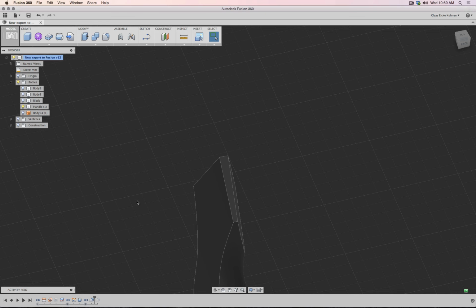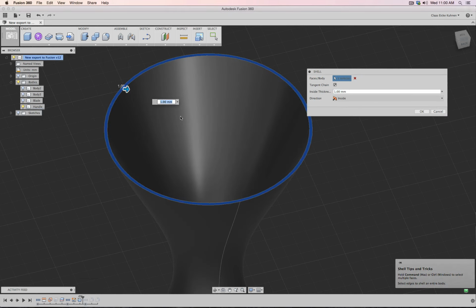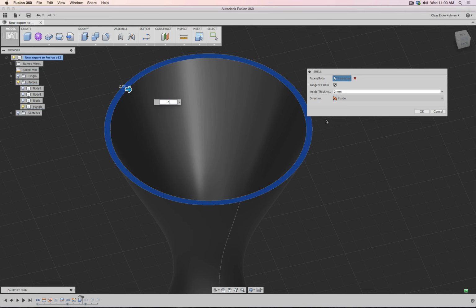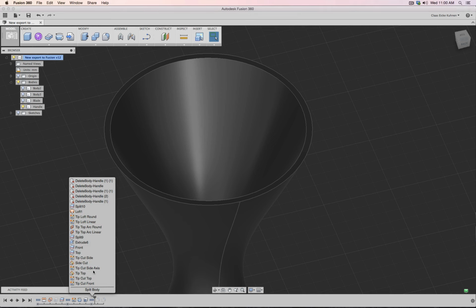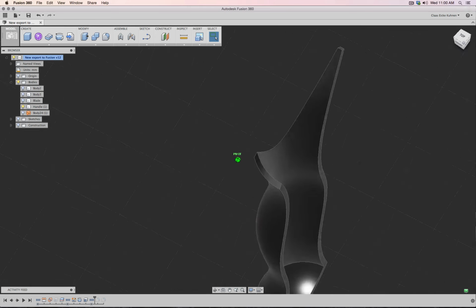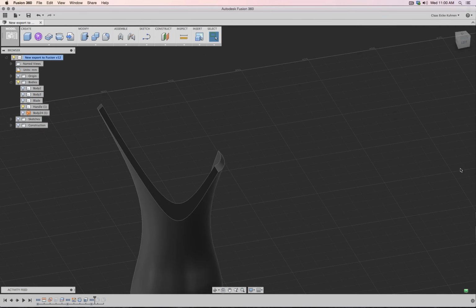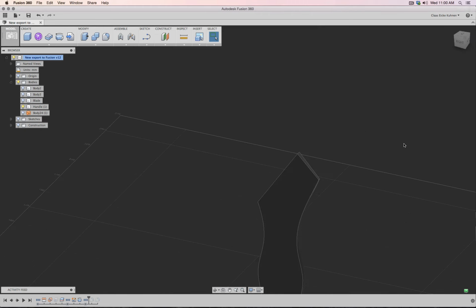Oh, much better idea. I go to here, there. This one I shell out here, in this step. 2 millimeters, please. Perfect. And let's see if we go back to here, if it all works, or does to a certain degree. Of course, I shelled the part and I cut this one out, so nice try, but the modeling logic I created beat me here.